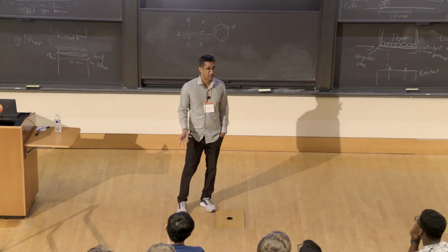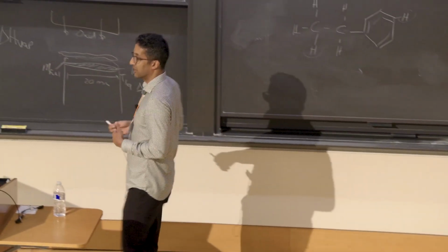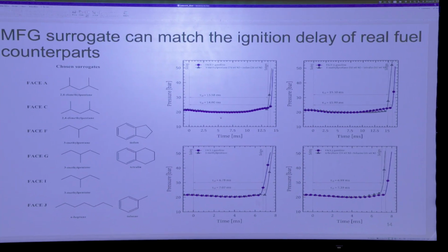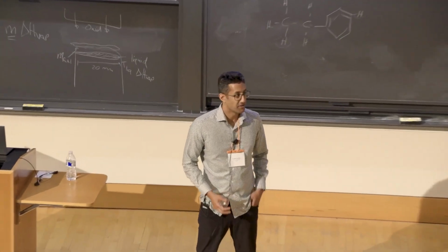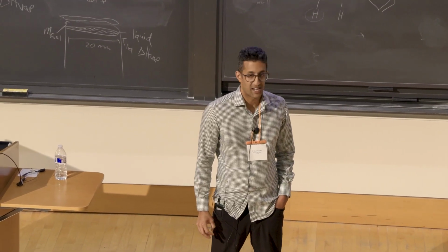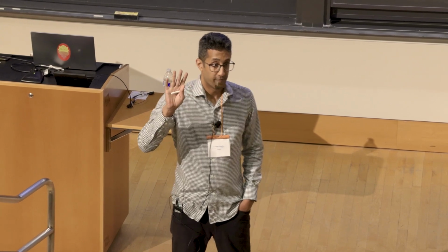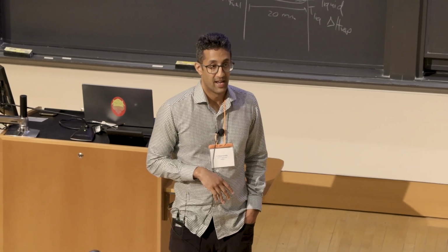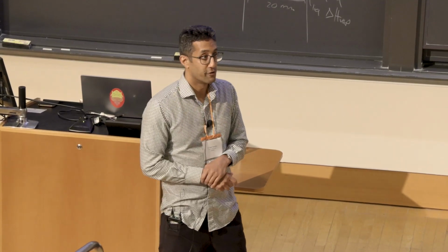And we started to notice there's some commonality. Even 1 component or 2 components matching the functional group gives you pretty much, within 5–10% error, the overall combustion characteristics of a real fuel. Okay? Now, is this to say that you're going to get the species formation exactly correct? Probably not. Yeah? Are you going to get the soot formation exactly right? We don't know. There's more tests have to be done. But it goes to show, at least, the functional groups appear to be the governing phenomena, or governing the kinetic phenomena, many kinetic phenomena in combustion systems. And with this knowledge, can you simplify your kinetic models? Can you make it easier now to model real fuels?